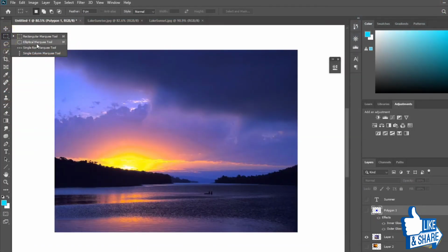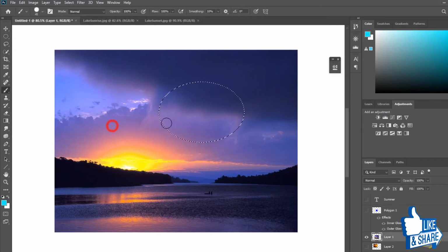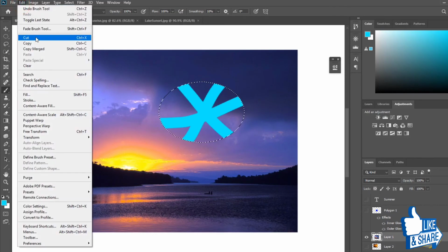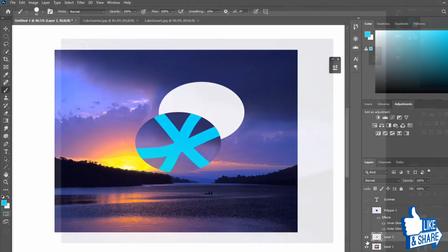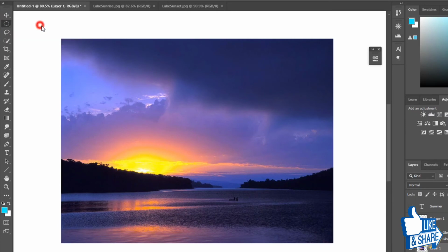Selection tools are used to select limited regions from the current layer in order to apply brushes and corrections just on these, or also cut, copy, and paste these as independent layers. Use the marquee tools to make rectangular or elliptical selections, and the lasso tools to make complex selections freehand, polygonal, or magnetic by following the color variations on the preview.